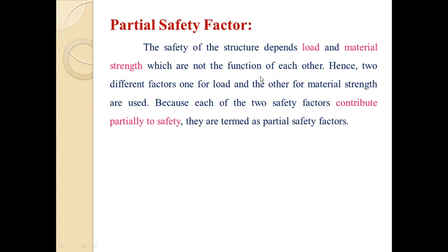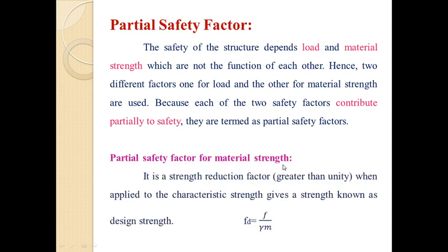That is, these two factors, load and material strength, are responsible for the safety of the structure. Therefore, these two safety factors contribute partially to the safety, and they are termed as partial safety factors. So let us see first the partial safety factor for material strength.